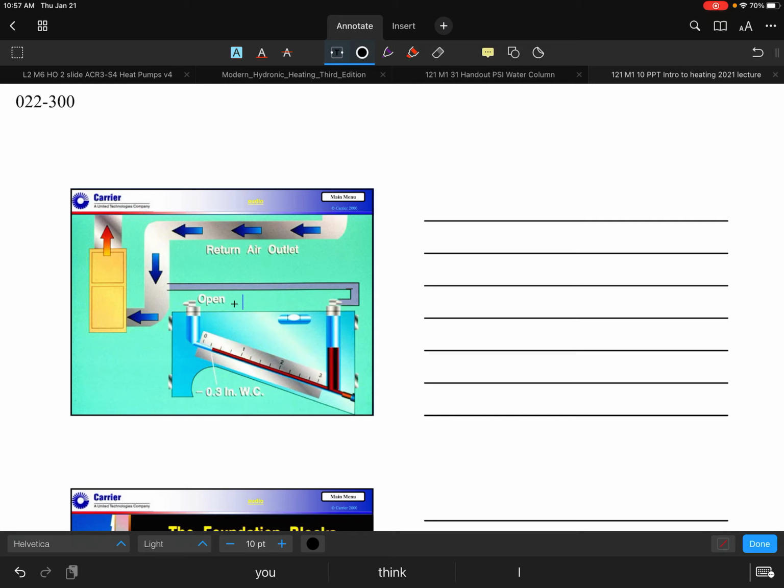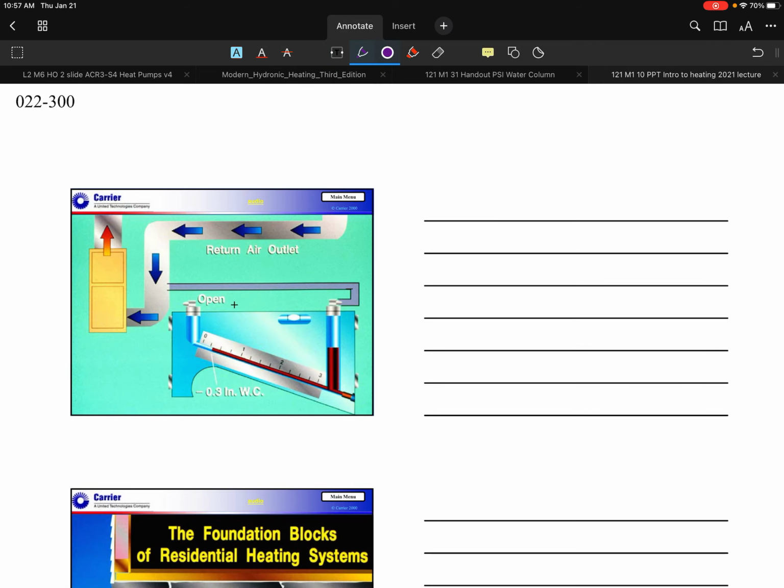Being that the fan is drawing that air from your main duct systems, and drawing it through this application, we know that it's negative, it's negative, it's negative, it's a little more negative, and so on and so forth. And we're seeing this in this particular case as a direct reading of 0.3 inches. So it's really the difference between it zeroed out and 0.3 inches. Now, those are examples of certain pressures that we would deal with.